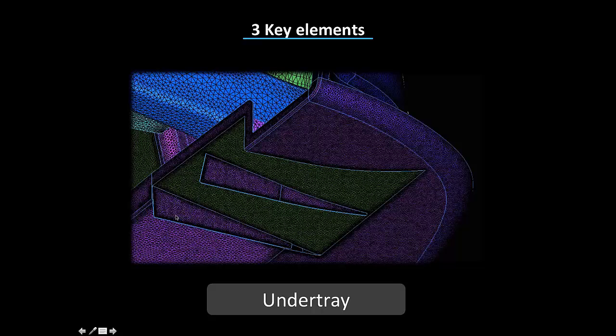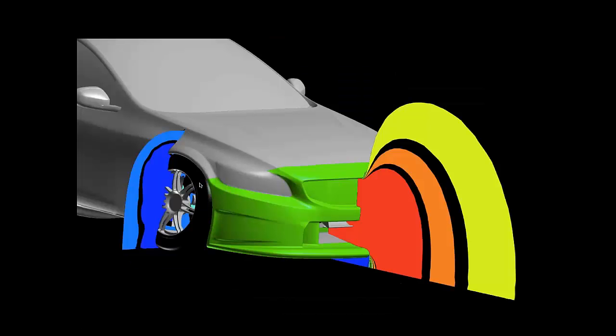They're handy for creating a streamwise vortex with a low pressure core that generally helps keep the flow attached in there, and also the cores help decrease pressure through those regions, so you can generate a bit more downforce with them. There are some limits to how many strakes you use on the front. I generally see 2 is what most people go for. I've seen up to 3. On the rear end you can use a few more.